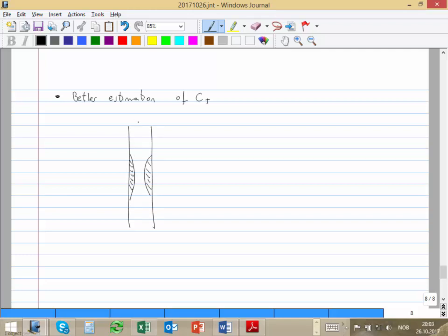Okay, and let's say you test that well and you say, well, it's producing much less than what it should. Okay, so what's happening here? So sometimes what is done is you come with a wire, okay, you put it inside and you start lowering down at different levels, and you measure the pressure, and then you get a curve. That will be pressure, and that will be TVD from 0 all the way to the bottom of the well, and it does something like this.